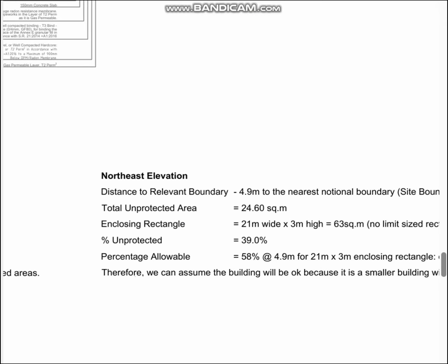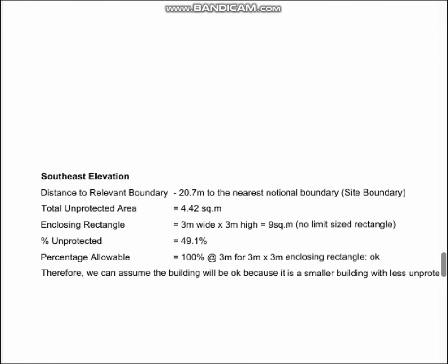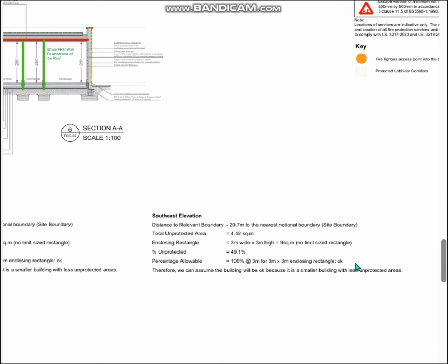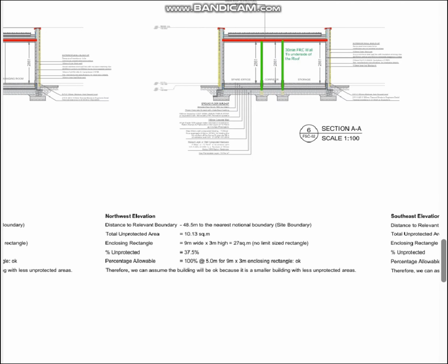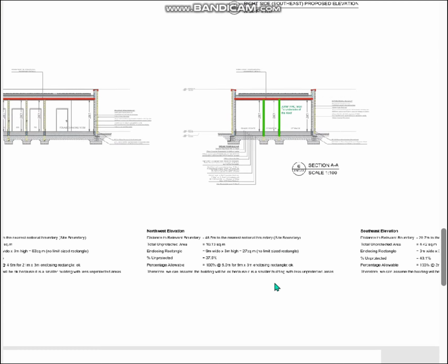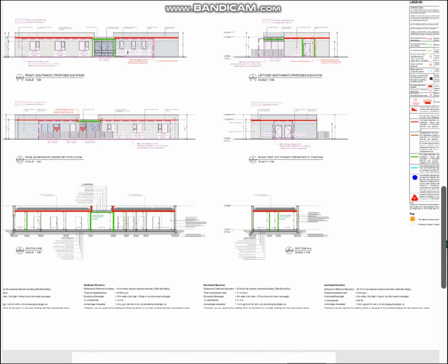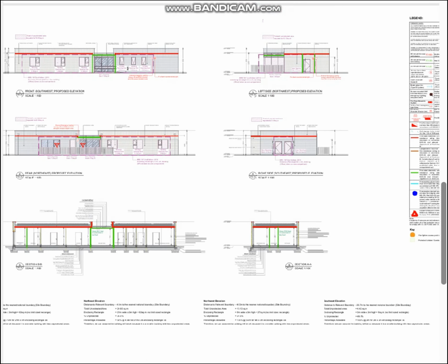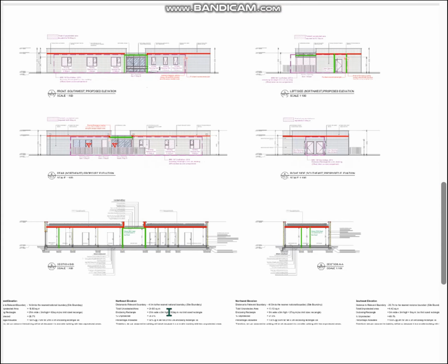This is usually carried out through BRE 182 external fire spread, building separation and boundary distance, and it is in accordance with section B4 external fire spread. Each elevation is taken separately for compliance.